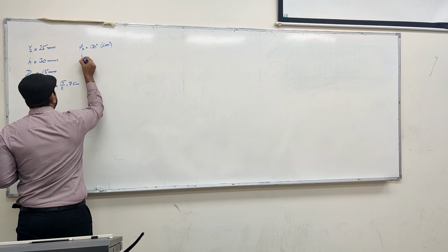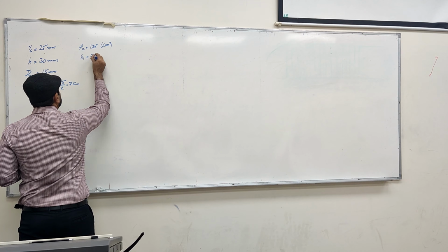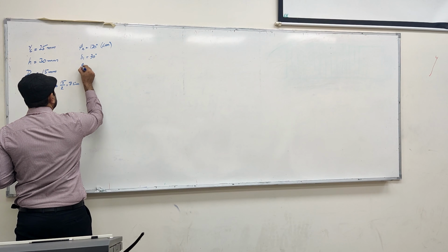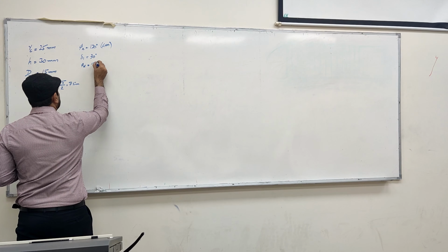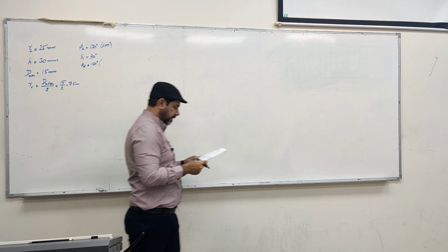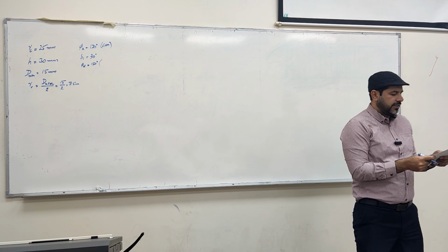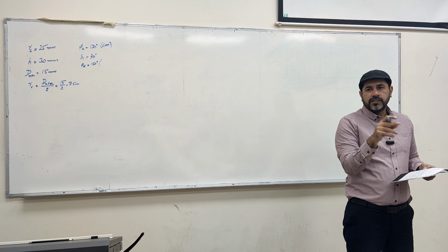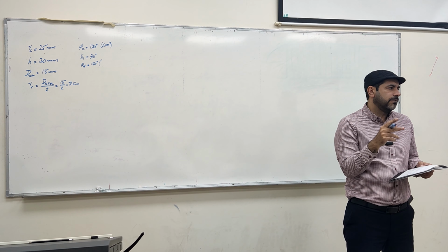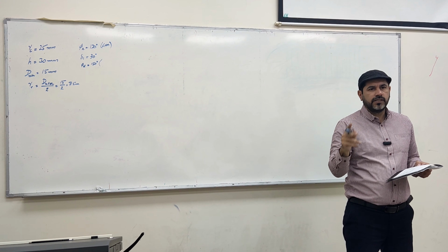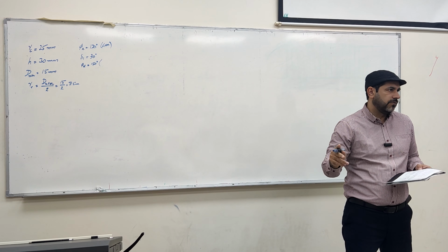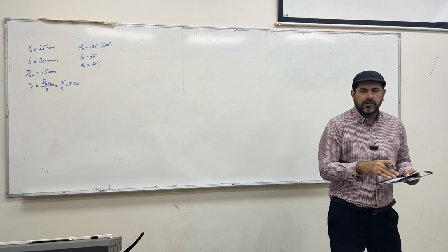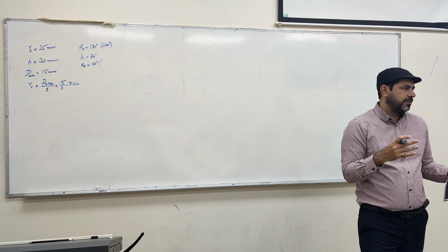And then dwell for 30 degrees. Then the follower lowers through 150 degrees, so phi D is 150 degrees with uniform acceleration and deceleration, followed by the dwell period. So the rest is dwell. Since we decided we'll stick ourselves to two conditions only: one is simple harmonic motion, another is uniform velocity. We can do this as well, uniform. Only some geometry is changed.